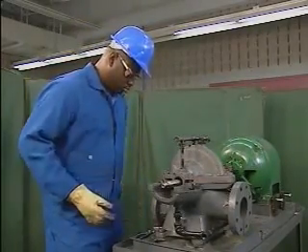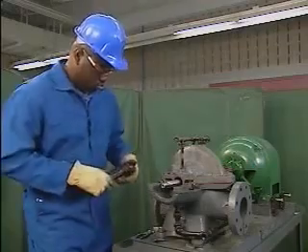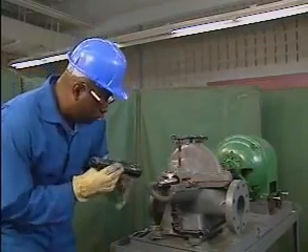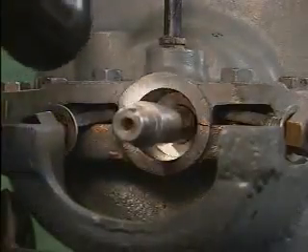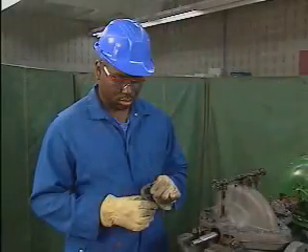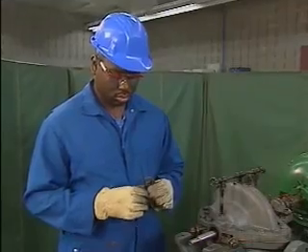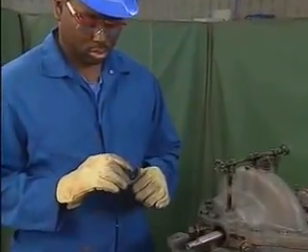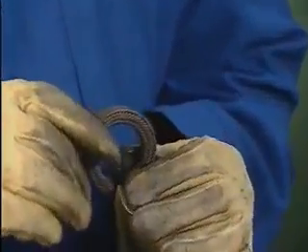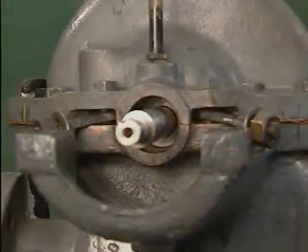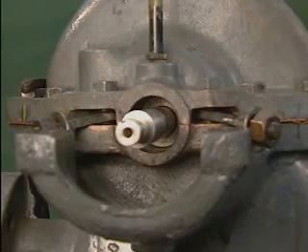After all of the packing is removed, he checks the stuffing box, the shaft, and the old packing for signs of damage. If there is any damage, it should be brought to the attention of a supervisor. The old packing is checked because it may show signs of damage caused by a damaged shaft. The shaft damage may be difficult to see from outside the pump. Now that the packing is completely removed, try a question on the material.